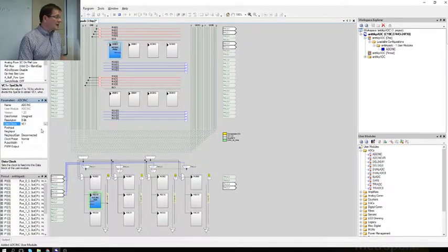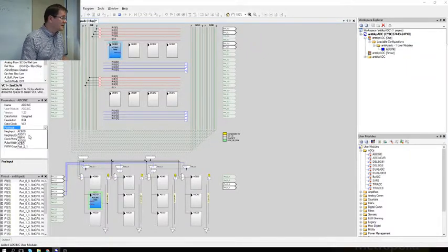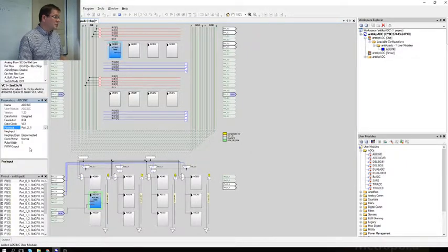The next parameter is actually the positive input, which is our signal input, and it has these 6 different locations you can take it from. I will just click on port 2.1 for now. Now it's hardwired into one of the ports. Remember, port 2.1 is actually not good, since that's also where this kit has the signal for the LCD display, but we will change that later on.